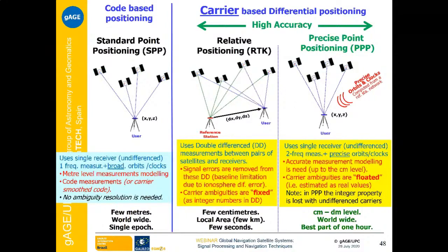On the other hand, because we are taking differences, be it single or double differences, the errors are removed or mitigated due to taking differences of measurements. Well, there is a limitation of baseline, but we can achieve this centimeter level in a few seconds.